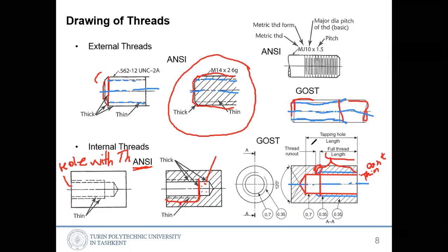So the hole again, and from the side view, the threaded depth should be shown with a thin circle like this, but a disconnected circle. Here it is not connected. Normally it is shown with a disconnected circle, where about 1/4 of the circle is not drawn.